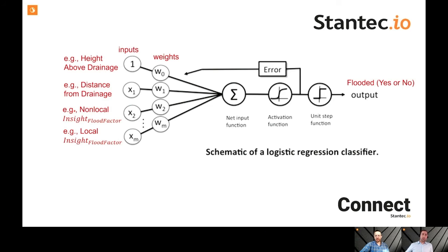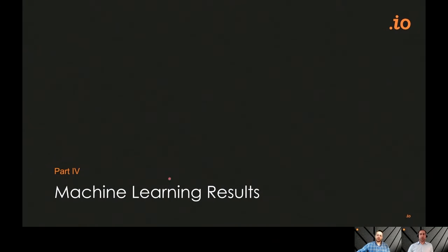But once we have that, we can supply different runoff values to get different levels of flood extents, as well as extending this to different areas where we haven't run a HEC-RAS model, supplying that runoff value and getting the flood extent. So it provides a way of using the HEC-RAS model to create a data-driven approach that has a life of its own for aiding in additional predictions to help save lives, to help inform risk, to help take mitigation measures, for example. And now I'm going to go into some of the machine learning model results that we observed for two different case study areas.